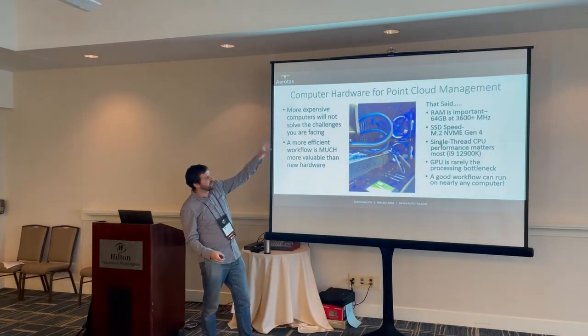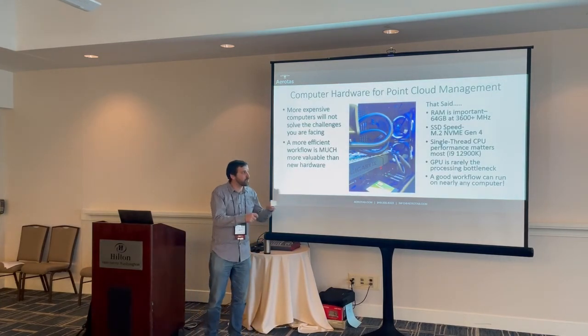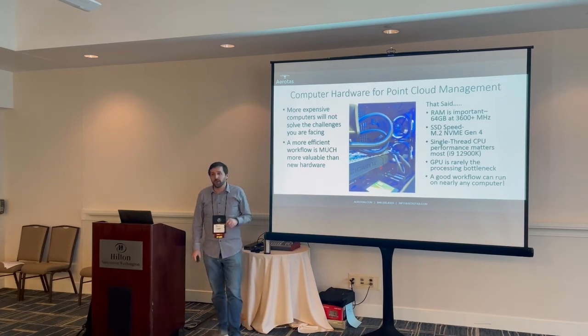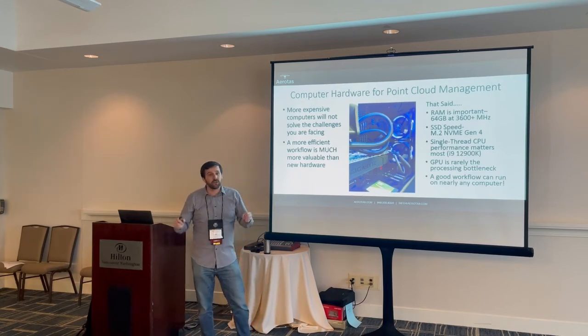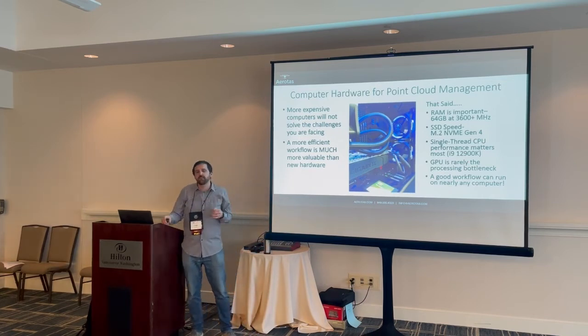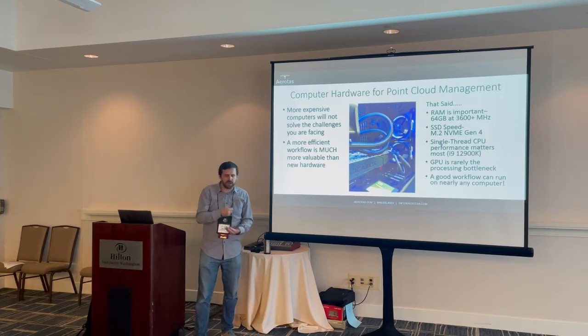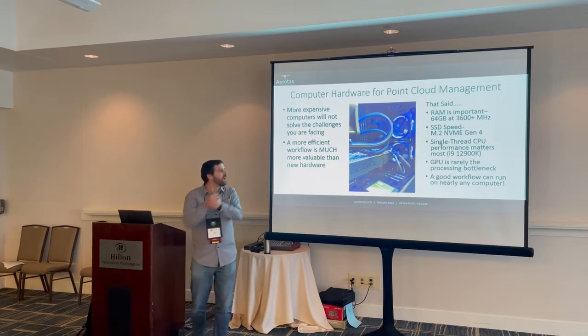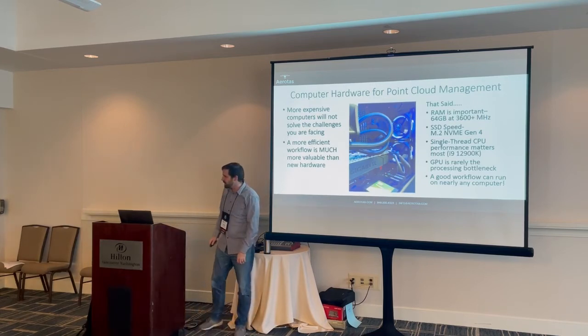So again, 64 gigs of RAM and your high-speed hard drive is going to be important, but a good workflow can run on nearly any computer. With photogrammetry, just so you guys are aware of how we think of it, we run exclusively on high-powered desktops. For our LiDAR processing and our LiDAR techs, we use gaming laptops. They're laptops. They're not nearly as powerful as our desktops because that's not really the bottleneck like it is in photogrammetry. Photogrammetry is much, much, much harder on computers than LiDAR. Buying really high-end computers isn't really going to fix major LiDAR problems.